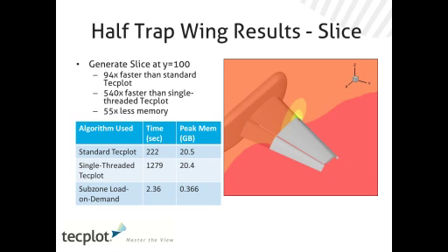But we take these subzone min-maxes of the input variables, the density, momentum, and energy, and do interval arithmetic to predict which subzones an isosurface is going to pass through. Then load only those subzones, do the calculation, and then calculate the isosurface.